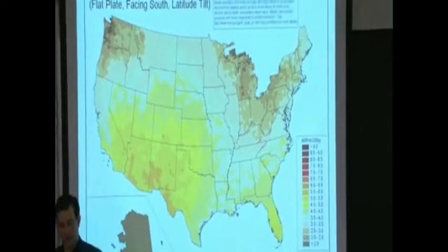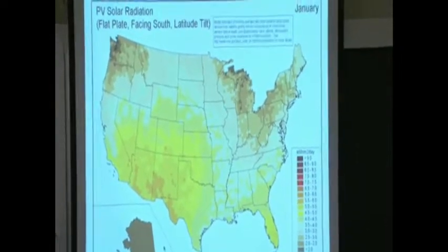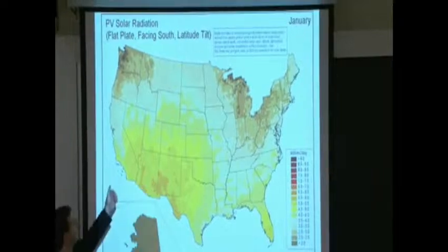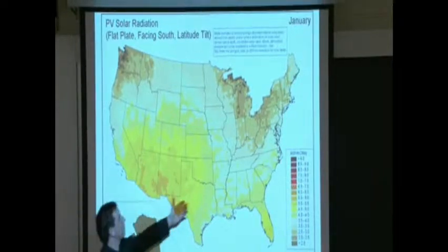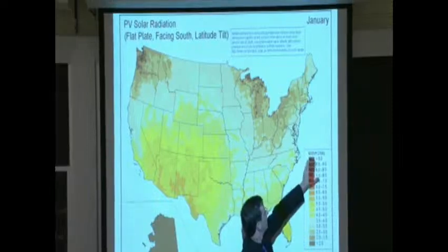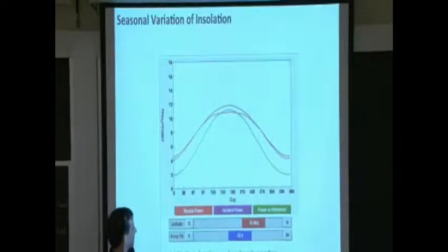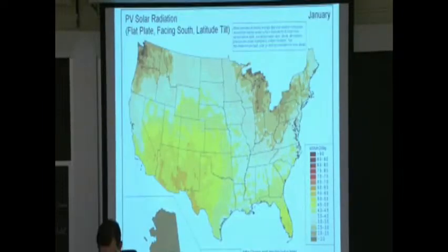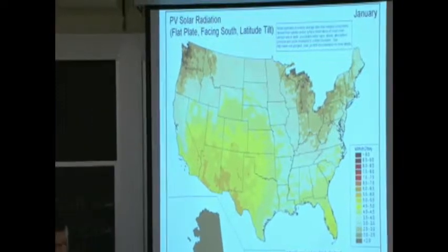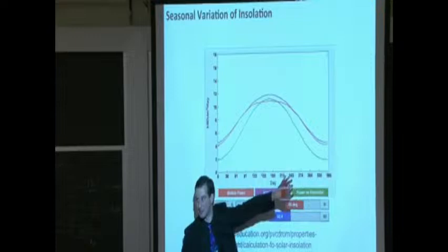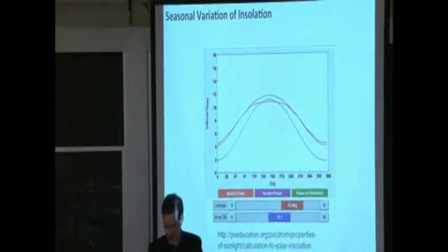And we can plot the total amount of energy per unit area per day, essentially the integral under that curve, as a function of location around the US, around the world, per month, let's say, right? So this is January. This is kilowatt hours per meter squared per day. So it's just taking the integral of the curves measured. So it's accounting for cloudy days, which has a depressive effect. This is an envelope function, if you will, the maximum you could get. And then, of course, local weather patterns will suppress that, drive it down.